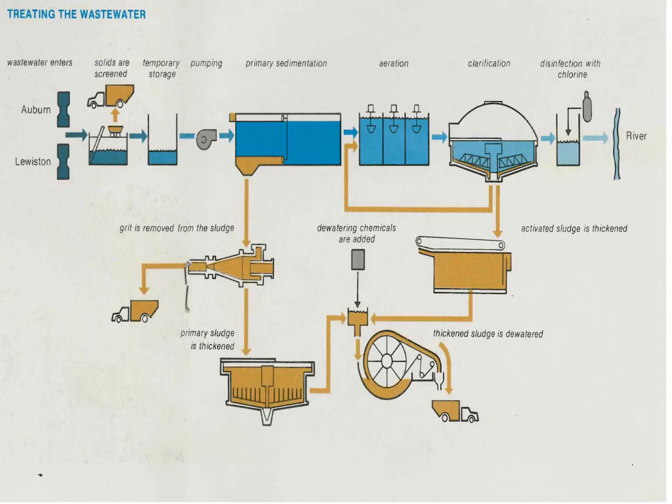This slide is the original process flow diagram for the Lewiston-Auburn Water Pollution Control Authority plant. I have it included here for a couple reasons. First off, it's interesting to see some of the old dewatering equipment that was used originally at the Lewiston plant, such as removing grit from primary sludge, which had a number of issues and has since been replaced. It also shows the dissolved air flotation thickeners that were originally used for thickening waste-activated sludge. Those have now been changed out to gravity belt thickeners.